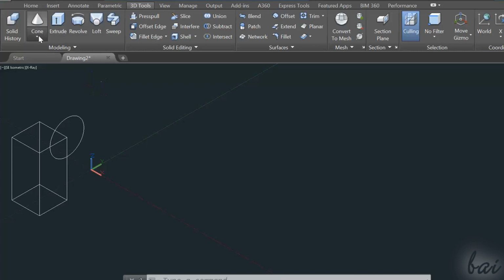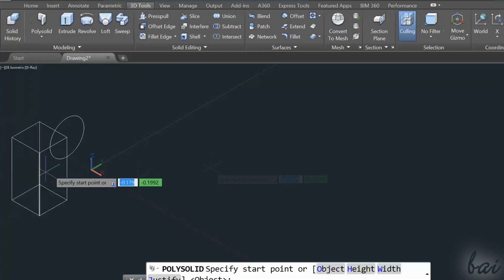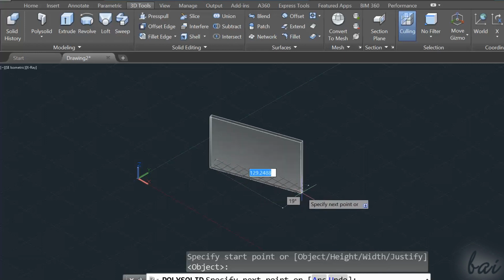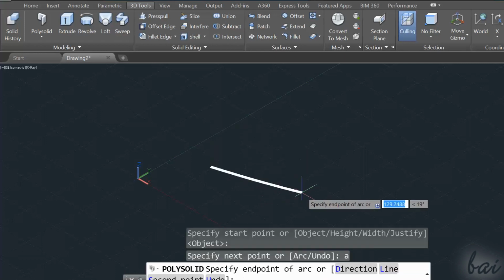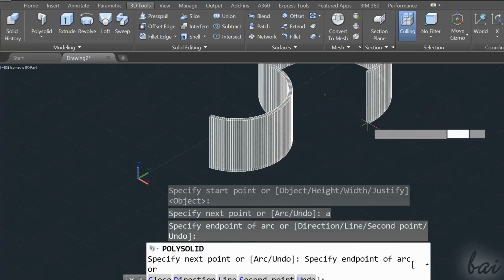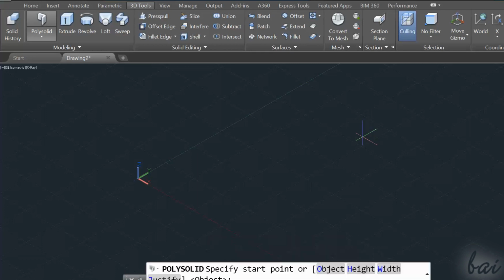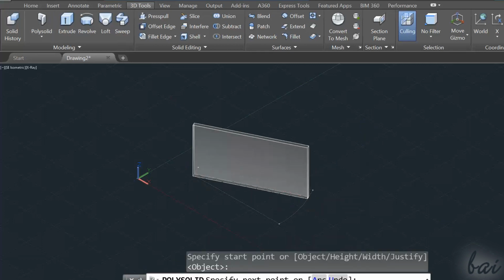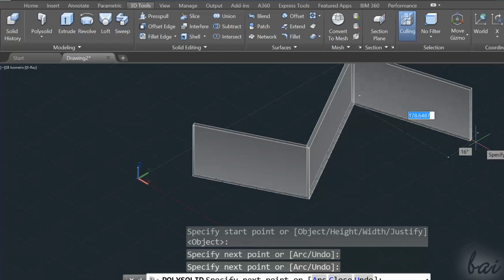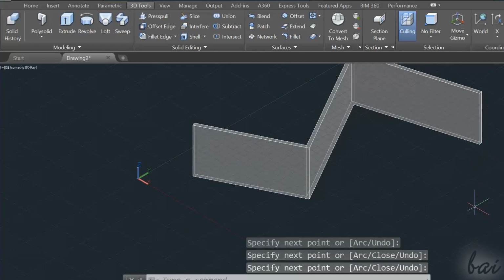In the first group of tools, you also have the Polysolid tool. This is useful to create personalized 3D regular objects. As you do with polylines, you just need to fix points, to place blocks with constant width and height, and the length defined by your clicks. Use Enter to finish drawing.